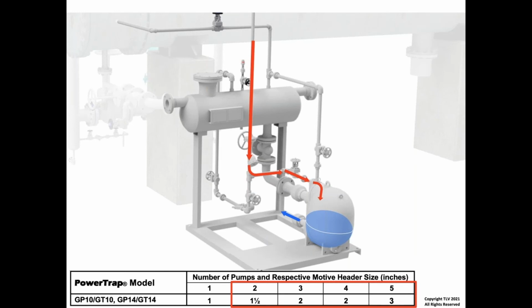So it's kind of funny. I mean, sometimes we walk on site, there was one of the applications we looked at not that long ago, had 3 large pumps on it, and it was being fed from a manifold that was a 1-inch manifold. Well, how can you feed 3 pumps without starving the steam going into the secondary pressure drainer when you need a 2-inch line and it had a 1-inch line?